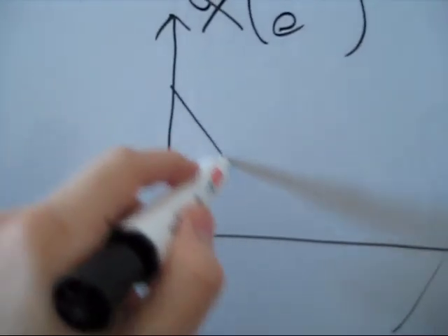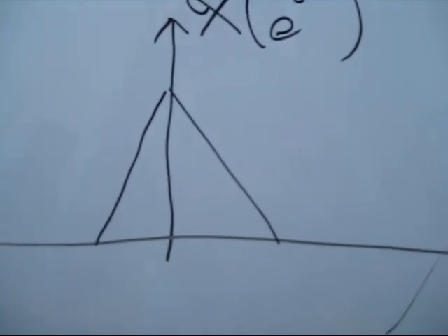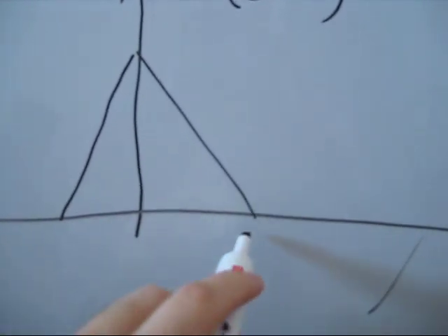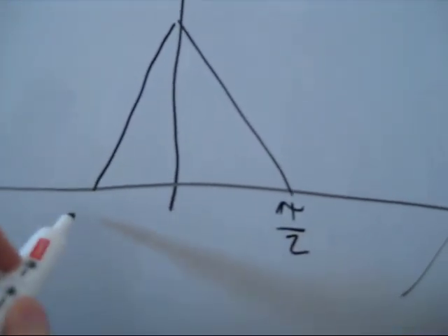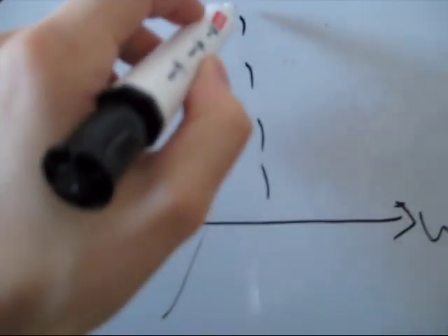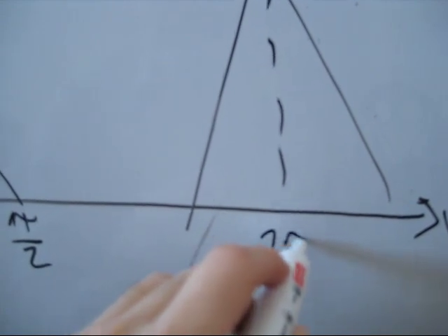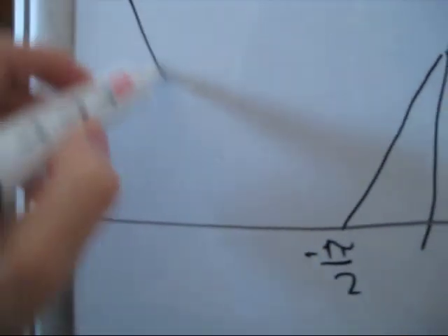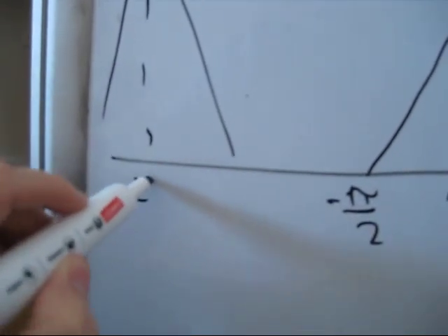So you've got your center here, and remember we've sampled at 4 times the Nyquist frequency. So this is going to be pi over 2. This is going to be minus pi over 2. And over here, you've got your replica, where this is 2 pi. And of course, you've got another one over here, and the center here is at minus 2 pi, right?